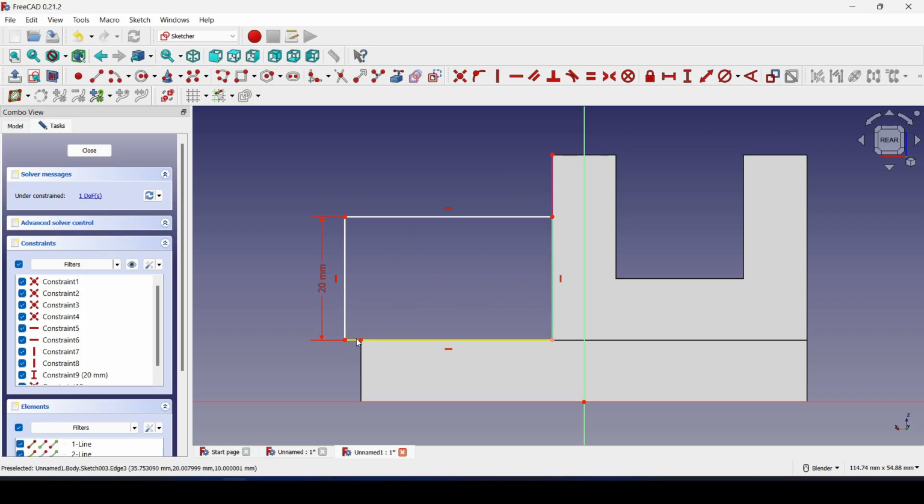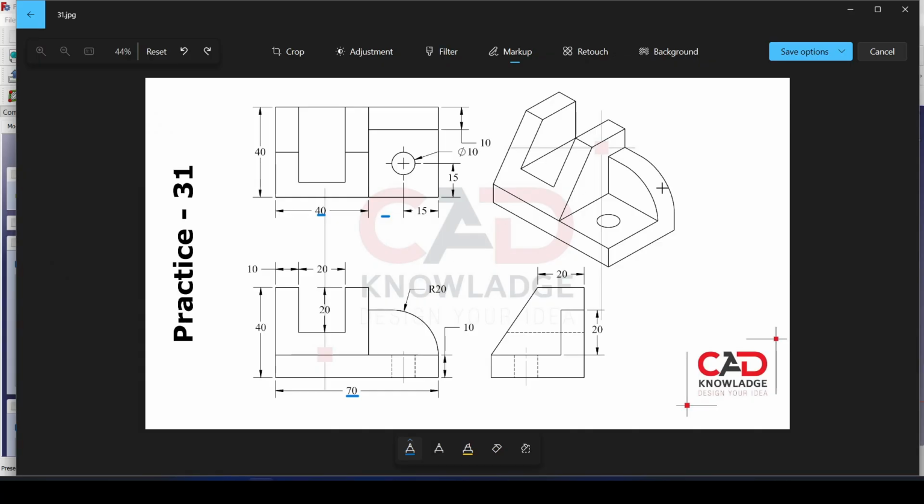And now we can see that our length of this object is a little bit long. So once again, I will just take our point here, coincident, and select these 2 points and then give it a coincident constraint. Okay, so now we're fully constrained, and you can see that we need to create a fillet in this design here.